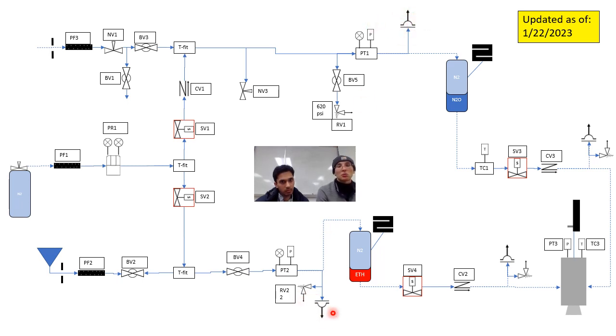So those are like worst case scenario. We get to pressures of like 1,000. Our pressure relief valve, like RV1 for example, is stuck, so it's not even venting at 620. Something goes wrong, or pressure increases so fast that the pressure relief valve cannot keep up. Then these burst discs are kind of our last hope, and they burst at a known pressure with some degree of uncertainty that we take into account.